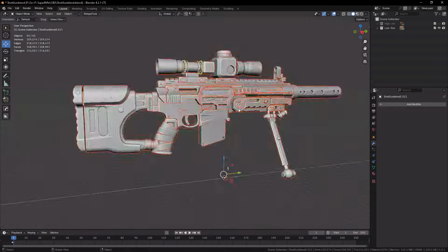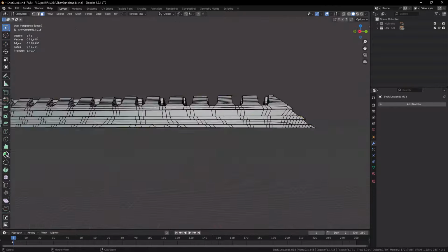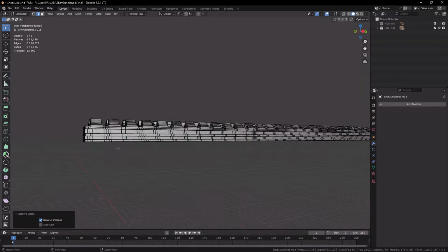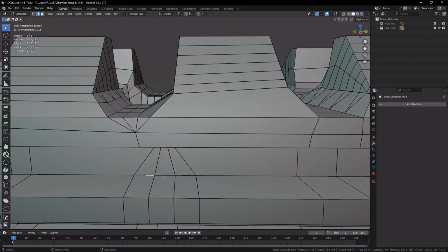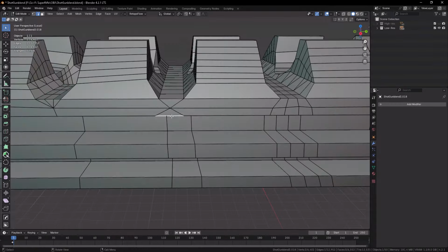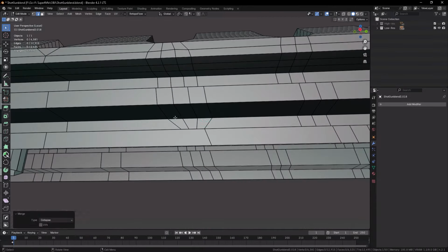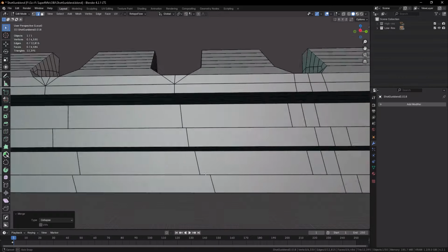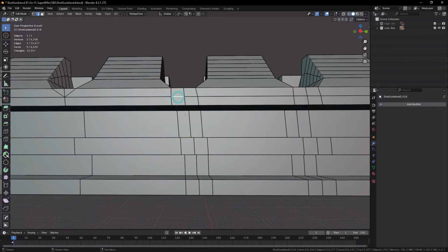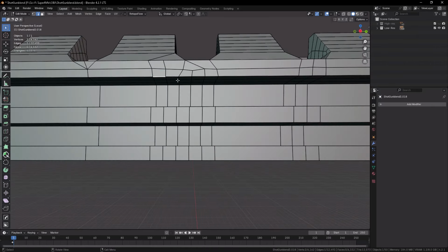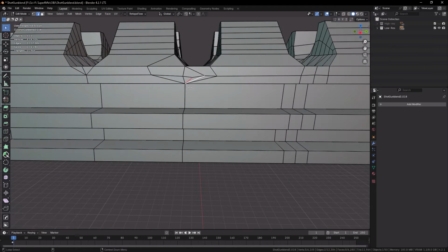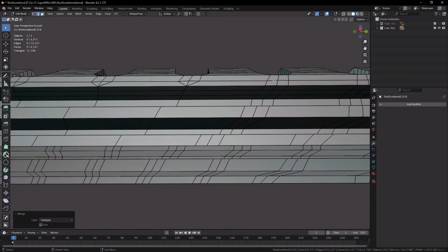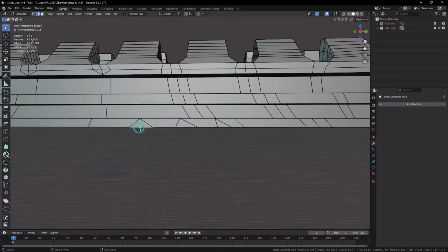On the other hand, you don't want to clutter your mesh. So the trick is to remove all the polygons, all the edge loops from flat areas. Just keep them edge free if that is possible, and concentrate most of the geometry on curvy areas to retain as much detail as possible. The low res mesh must resemble as closely as possible the high resolution one. Okay, that's the trick you want to go for.